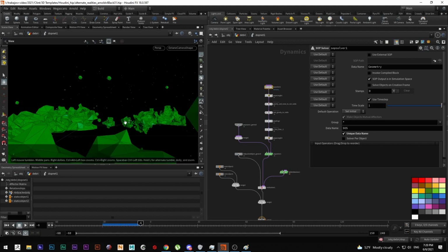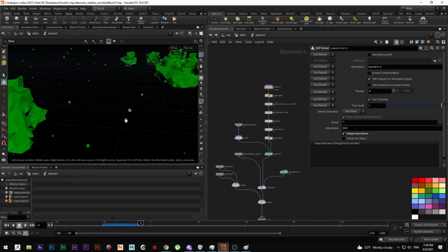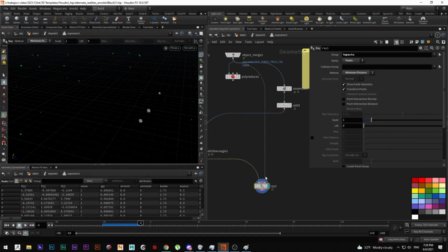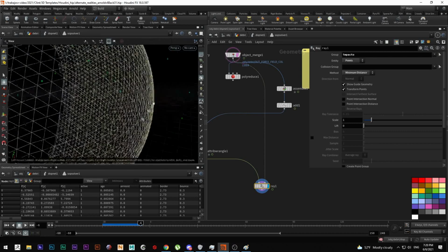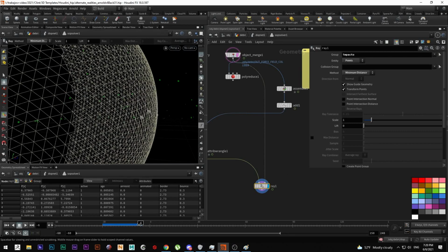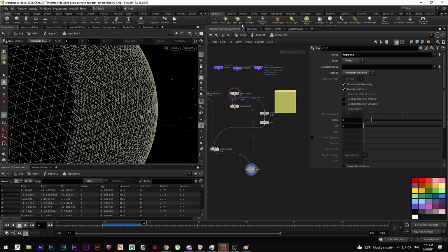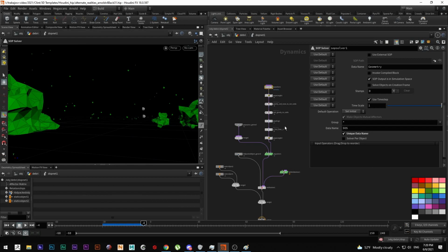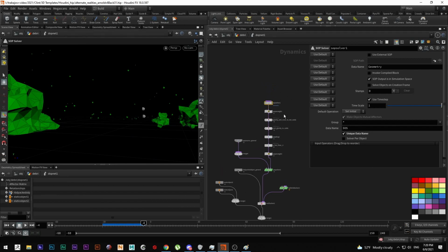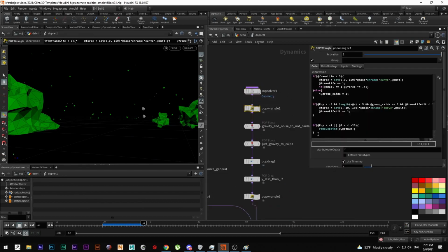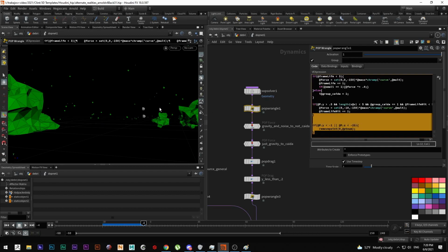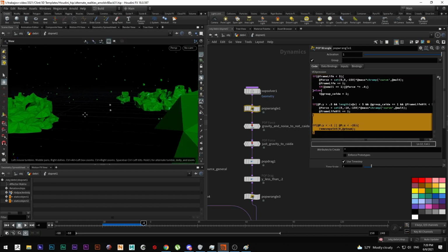See how these are turning white? These are the ones that are colliding with the geometry. They're red for 2 frames because in order to instance some sources, some volume source, you need to stick them into the surface. At least 2 frames. Otherwise, you are not going to generate any smoke whatsoever. With this code, I can create some motion.